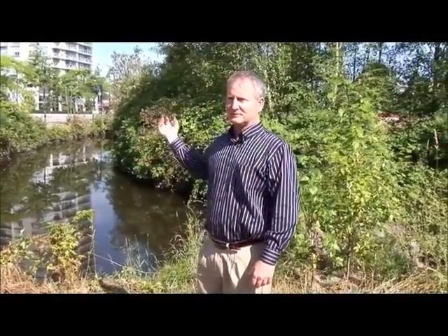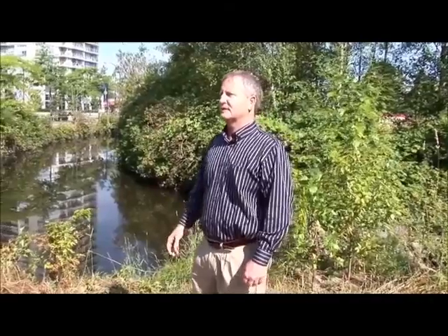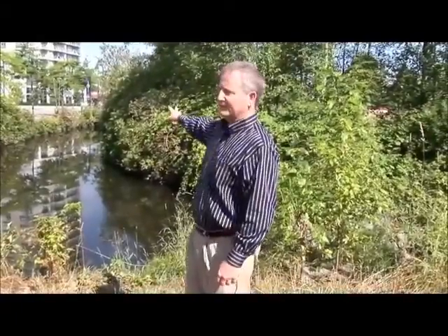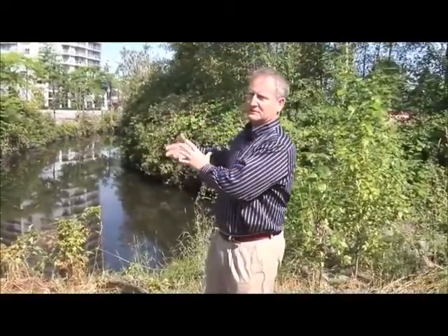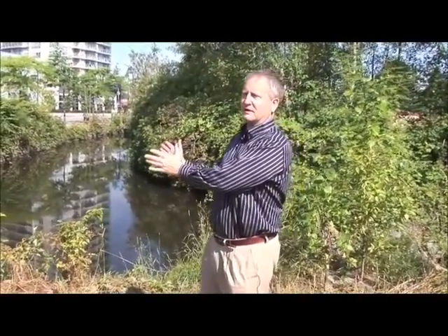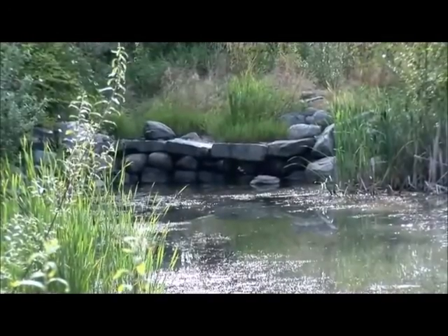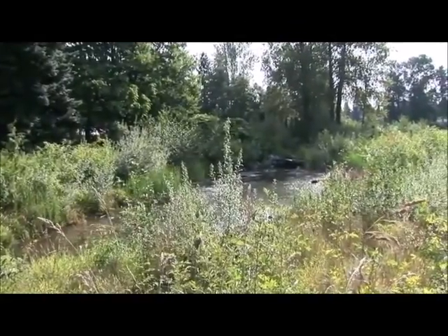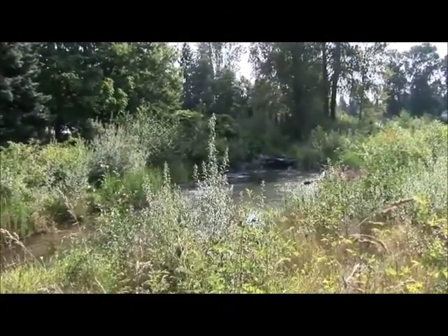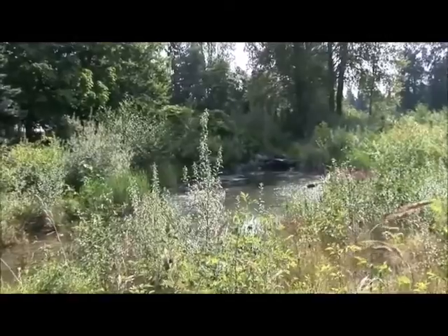As time goes by and the water quality improves coming from upstream, we have very little maintenance at all. That bay in there is a sediment trap. So we can actually come in, excavate down to the lock blocks that are at the bottom without affecting too much of the habitat. Wetlands are even more effective designs because they not only store and absorb large quantities of runoff, but they are effective purification systems.